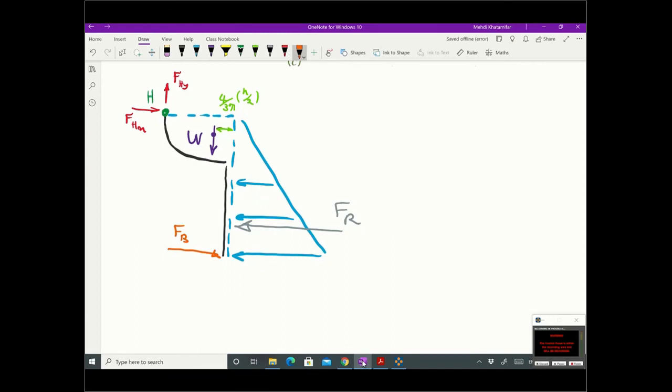No, centroid is different than moment of inertia or yr. Centroid, for example, for the square, is the center. For circle, center. For triangle, 1/3 from bottom. Center of pressure is something else.